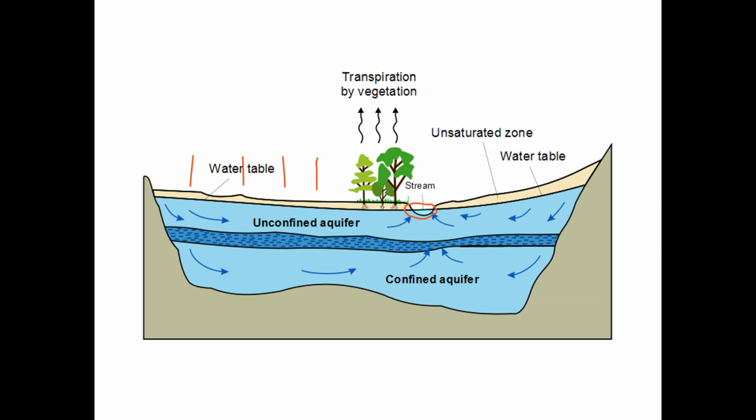So that's a boundary condition. And then, let me change colors a little bit. So this entire boundary, it kind of blends in there, that I'm tracing along this side. This is what we call a no-flow boundary. We have an impermeable layer underneath this system, and so if we say water cannot pass through the bottom, that's a type of boundary condition as well.